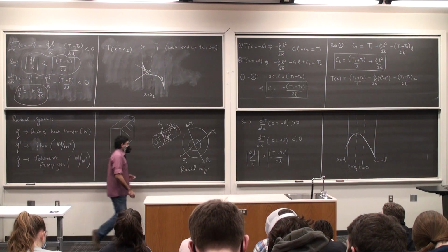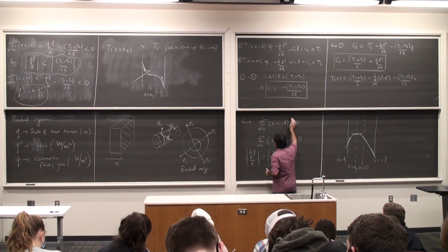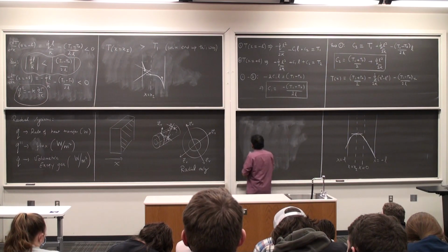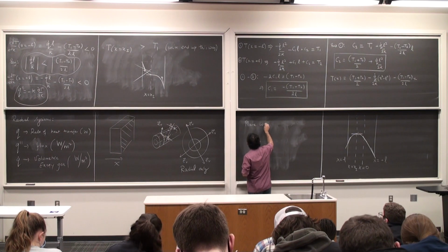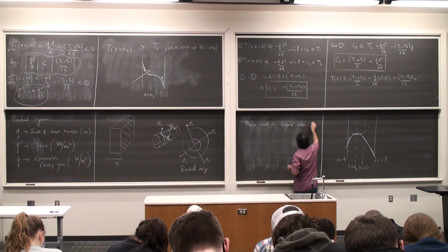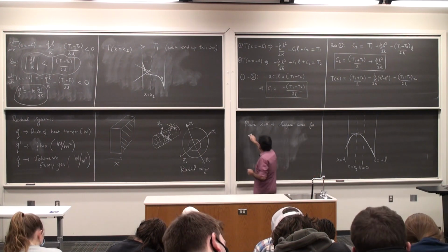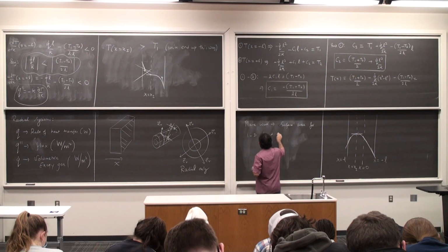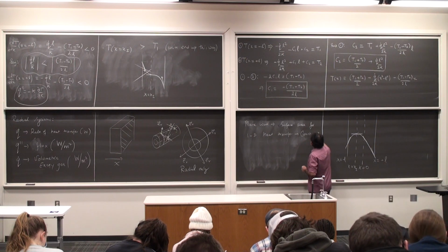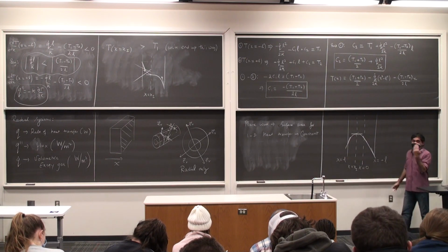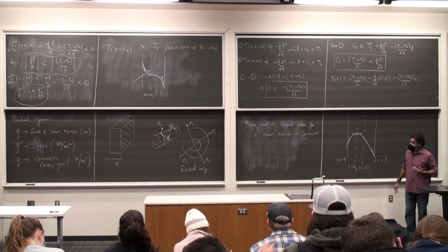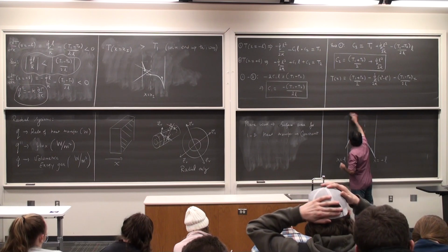So for a plane wall, the surface area for heat transfer is constant. As you can see, that's a shaded area. As I travel along the x is equal to 0 or minus L or plus L location, surface area never changes. That's not the case for cylindrical bodies.